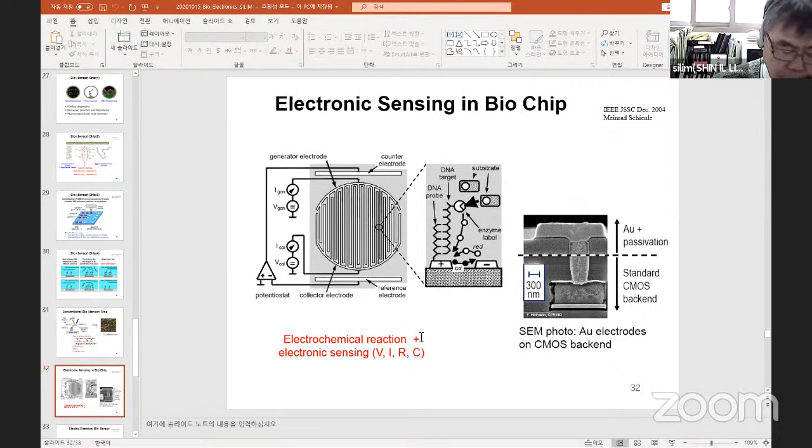Applying simultaneously an oxidation and reduction potential to the sensor electrode, about several hundred millivolts with respect to the on-chip reference potential, the oxidation and reduction process generates currents at the electrode. A potentiostat, whose input and outputs are connected to the reference and to a counter electrode respectively, provides the difference current to the electrolyte and regulates the potential of the electrolyte to a constant value.